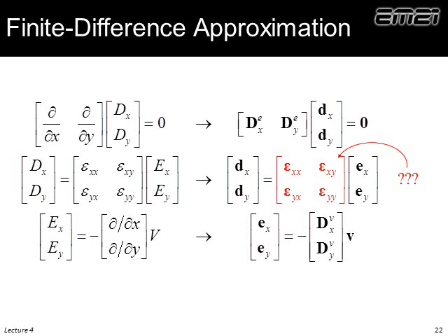Now we write this in matrix form. Based on what we did last semester, we don't actually have to touch the finite differences explicitly. We can take our analytical derivatives, and these are our derivative operators for taking derivatives of the electric fields. Our D fields are column vectors, so they have these bold lowercase d's. Our constitutive relation becomes this matrix equation. We'll talk a little about that in a second. And then the electric field is related to the scalar potential through this equation, and now we have derivative operators operating on the scalar potential V. Now back up to the constitutive relation. This demands more attention because in fact this is not correct as written and we need to modify it.